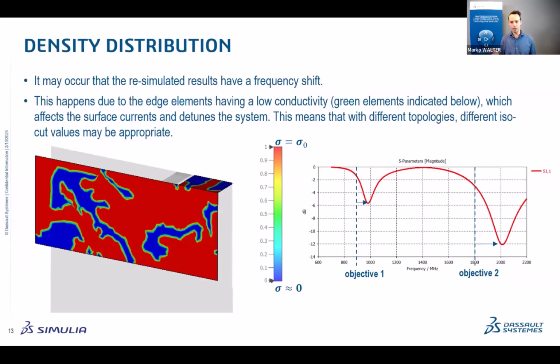Now, let me try to explain a bit why we need these. So with the topology optimization, the original integer problem is basically relaxed here, allowing a continuous and intermediate sort of design variables. So these so-called intermediate densities allow for a mathematical programming approach, basically, using adjoint sensitivities.